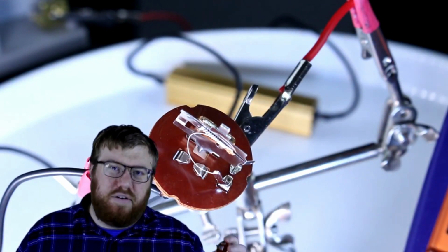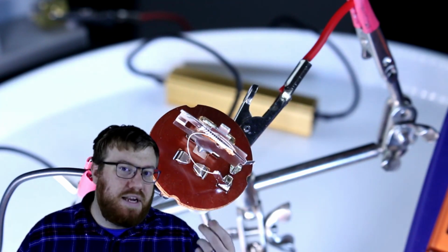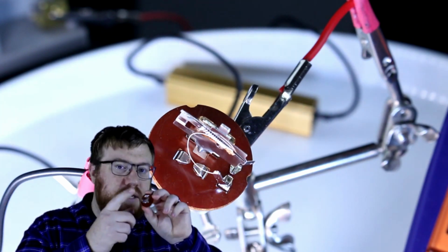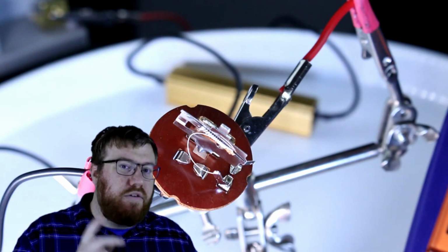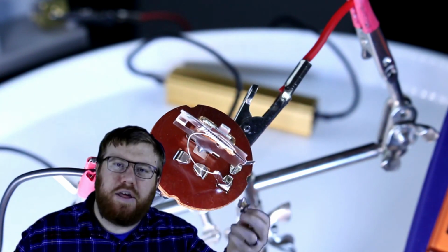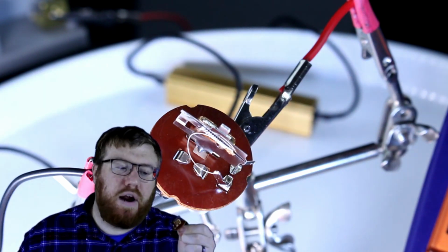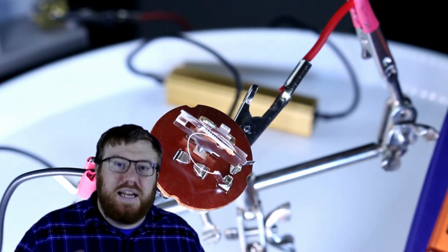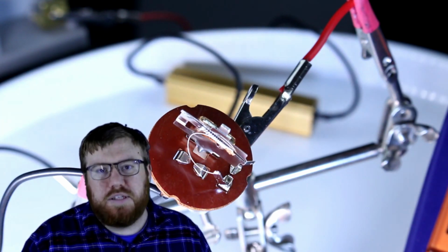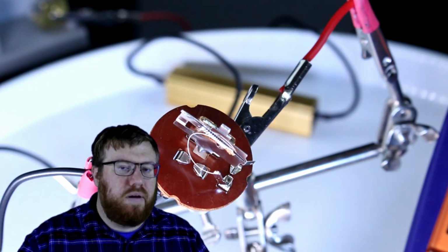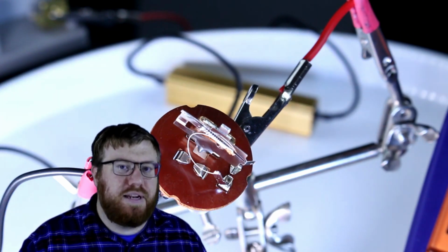On this particular model, electricity has two different paths that it can take to get from one pin to the other, and sometimes one of those paths isn't available. The path that is always available is a tiny wire that's wrapped around a strip of metal. That tiny wire can't handle the amount of current that's passing through it, so it starts to heat up. More importantly, it heats up the strip that it's wrapped around.